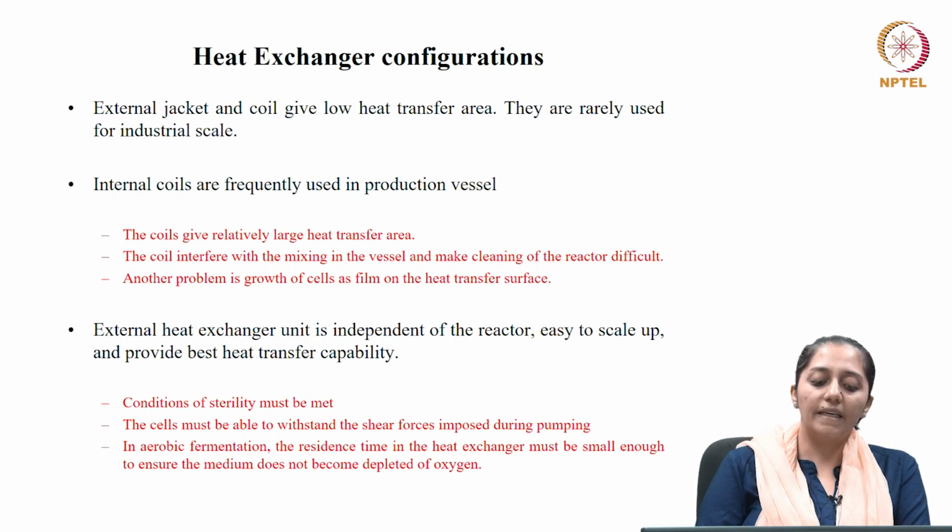Now, the external heat exchanger unit is independent of the reactor, as I mentioned. It is therefore easy to scale up, and this can provide the best heat transfer capabilities. However, the points to be considered include that the conditions of sterility have to be maintained, because now the fermentation medium is going outside the reactor.